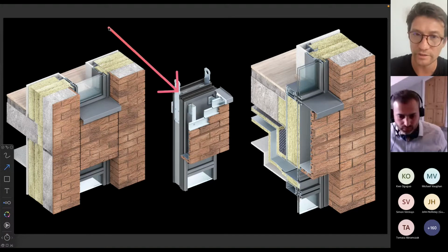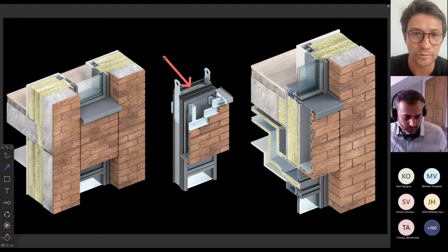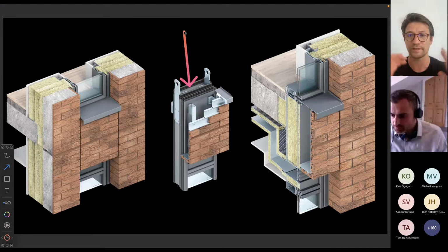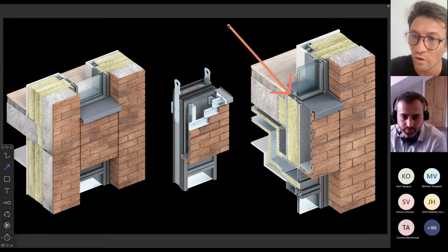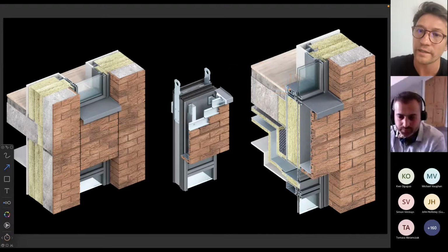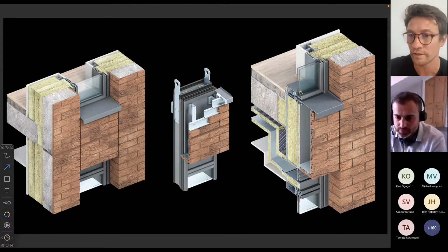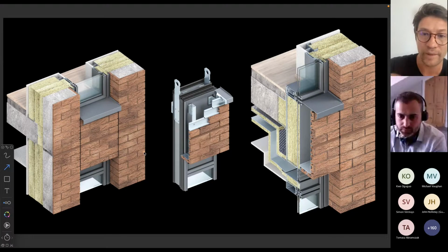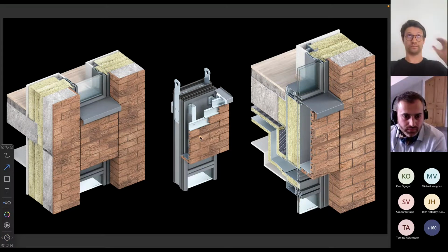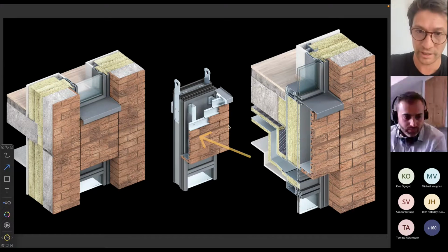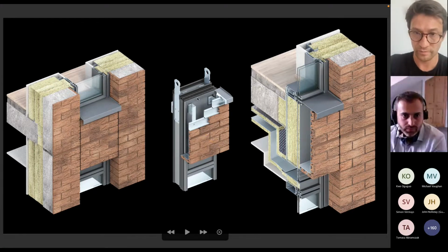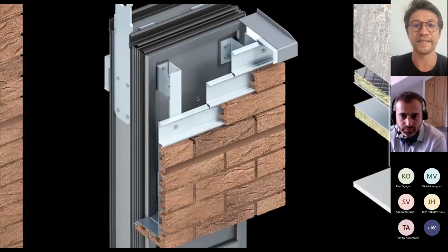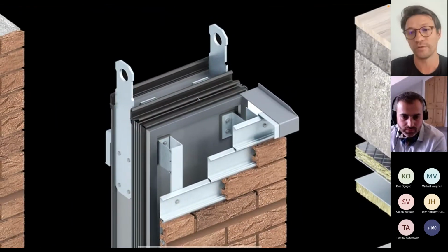So this is a unitized system. This particular profile could be whatever the unitized facade is. So this could be Schuco, Aluk, Reynaers, Veneer, whatever it is, and that only serves as a backing structure. Now, to this backing structure, to that unitized system, one could install any brick slip system that I just mentioned. This particular one that you see on the screen right now is Corium. This is the Corium brick slip system that is fixed to the unitized system of the curtain wall.